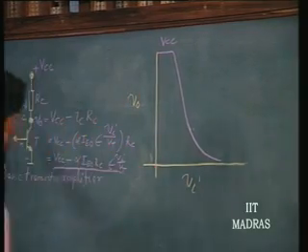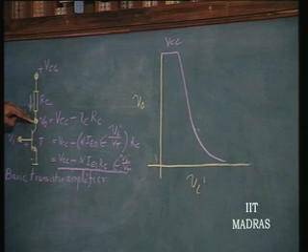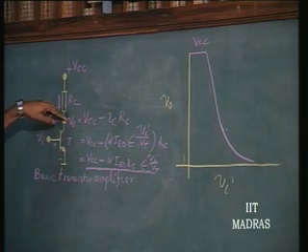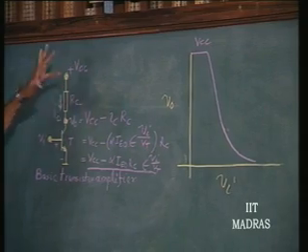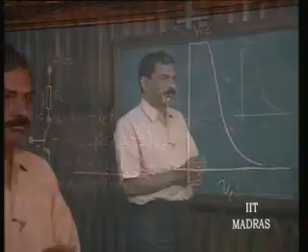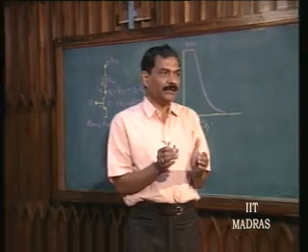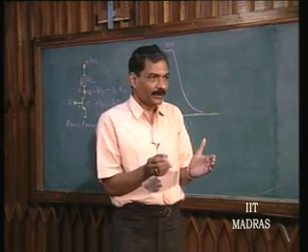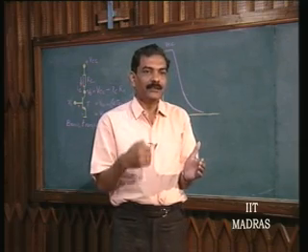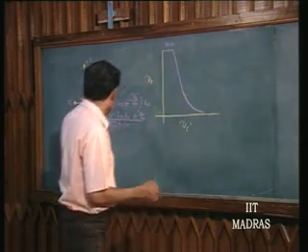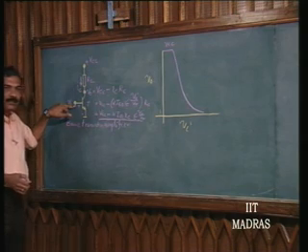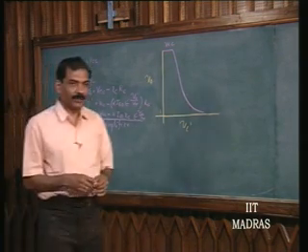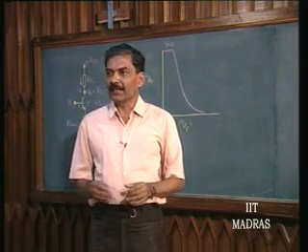That is, the moment this voltage reaches about this Vi plus V gamma, or let us say Vi plus 0, that is VCB equal to 0, is the point where it is entering the saturation region. So, this collector base potential should be reaching 0, or VCE should be reaching V gamma. Okay. So, that is when it is entering the saturation region.